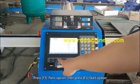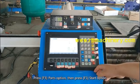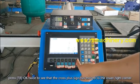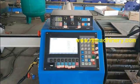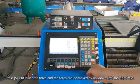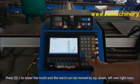Press F3 Parts option, then press F1 Start option. Press F4 to select the lower right corner. Press F8 OK twice to see that the cross plus sign has moved to the lower right corner. We move the cutting torch to the lower right corner of the steel plate. Press S to lower the torch, and the torch can be moved by the up, down, left and right keys.